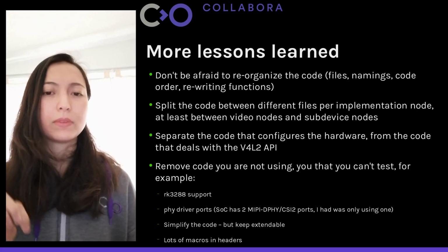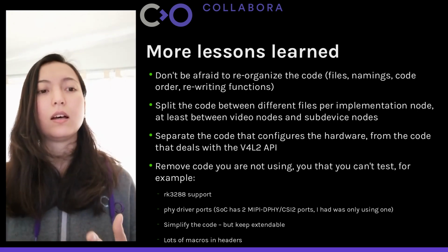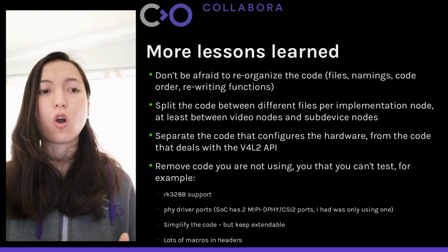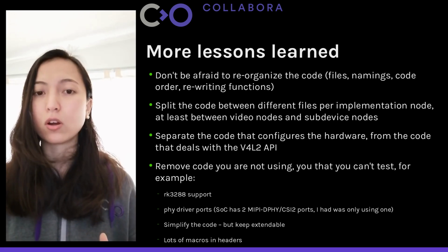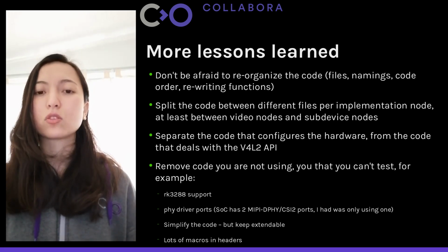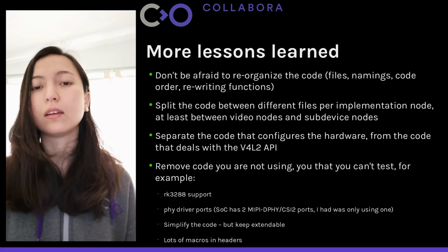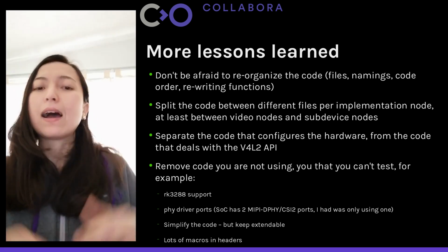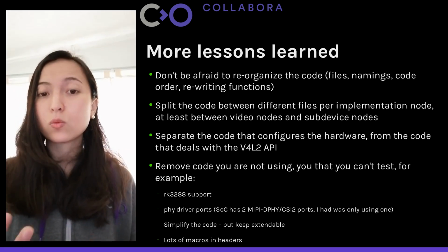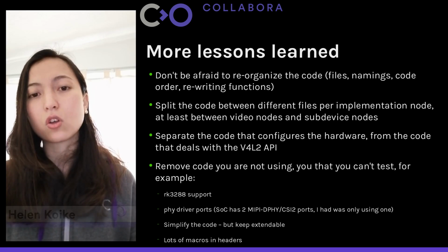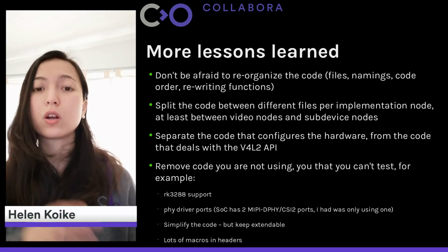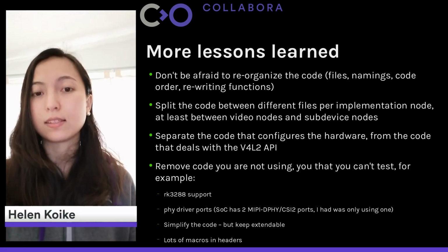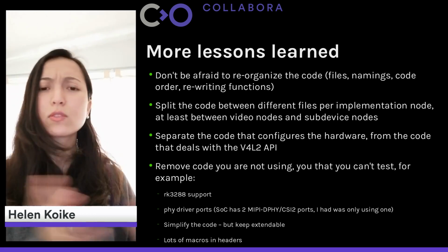Also, the PHY part of the driver had support for all the MIPI DPHY CSI ports, and it also had support for the DSI port. I was not using this one, and most of the boards that I saw were also using just a single port. So just remove everything.